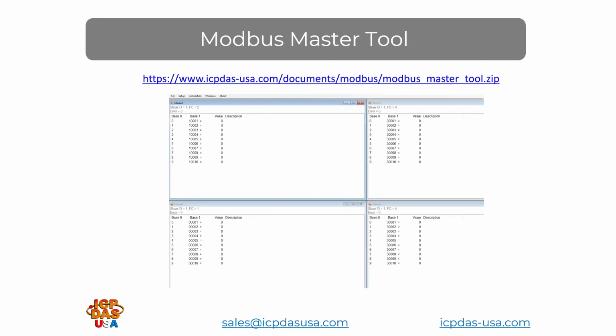Since Modbus devices traditionally give raw values, you can use this tool for assistance in scaling your analog values. It's very helpful in verifying if your software is reading the values right, or if your device is not putting out the right value. Almost all the time, it's going to be the scaling on the PC side or the number format.